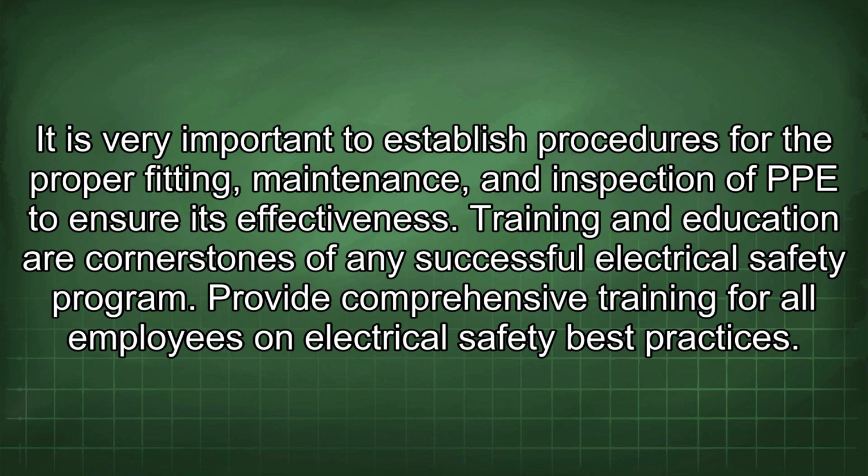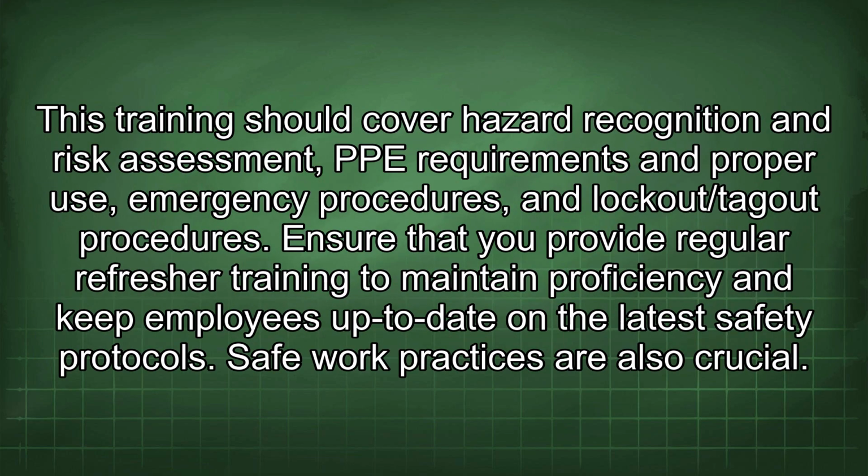Training and education are cornerstones of any successful electrical safety program. Provide comprehensive training for all employees on electrical safety best practices. This training should cover hazard recognition and risk assessment, PPE requirements and proper use, emergency procedures, and lockout/tagout procedures. Ensure that you provide regular refresher training to maintain proficiency and keep employees up to date on the latest safety protocols. Safe work practices are also crucial.